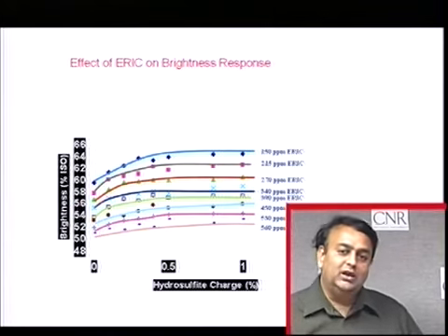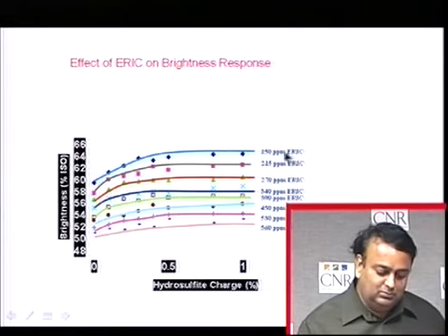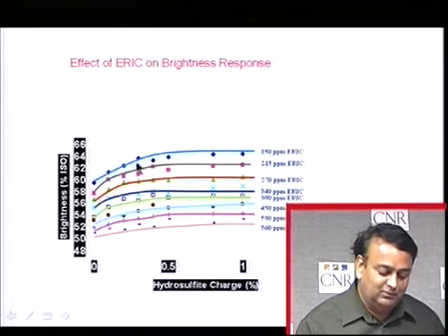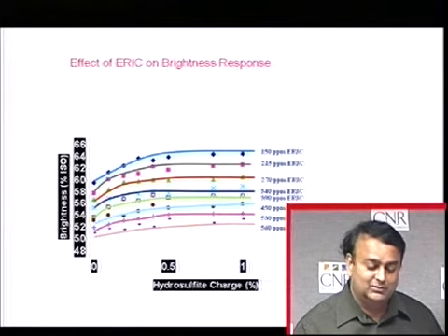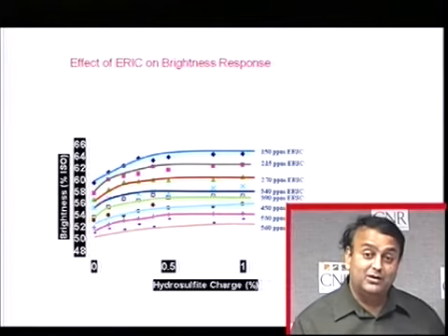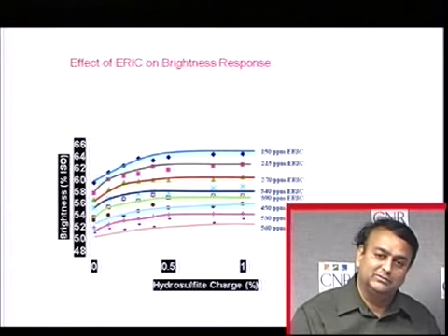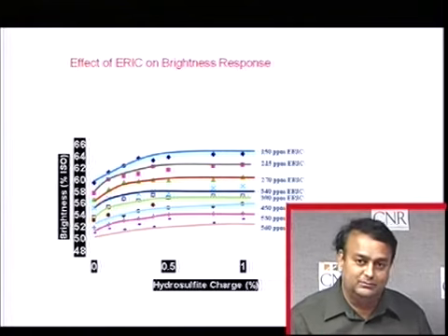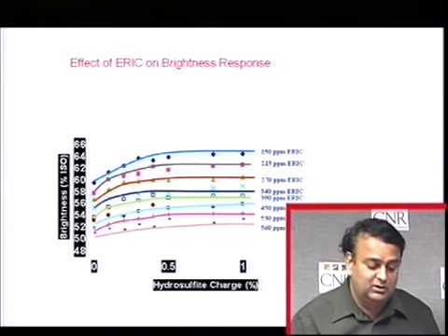As you remove the ink with the flotation step or washing, your ERIC goes down, you get a good response, it quickly takes off. 2 to 3 points you get with hydrosulfide bleaching. So where in the process do you add hydrosulfide? Typically you add at the end of the process, not at the beginning of the process where you have a high amount of ink. So point of addition is extremely important for bleaching.